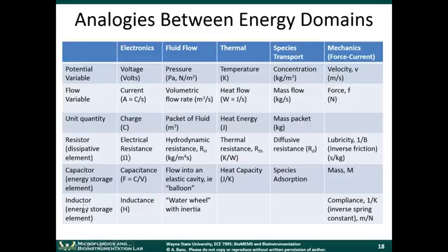The inductor is also an energy storage element. We didn't really talk too much about inductors in the fluid flow and the thermal domain, but we all know what inductance is in the electronics domain. It's energy storage in the form of a magnetic field. In the mechanical domain, the spring is represented by an inductor in the force current modeling mechanism. Whatever the spring constant is, the compliance is 1 over K, where K is the spring constant. And this is represented by an energy storage element.